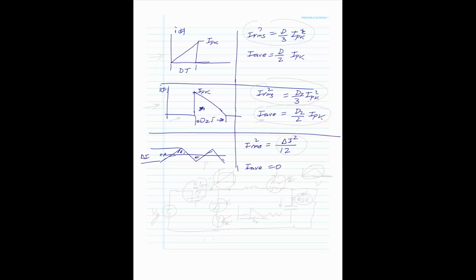So the cool thing is, if we're in, say, a buck converter, and we know this is the RDS on, and this is the inductor, and this is RW, and even the ESR, we know that the waveform in here is this waveform right here, the delta. So we can calculate the power dissipated here from this equation right there. Bingo, we're done. We got that one.